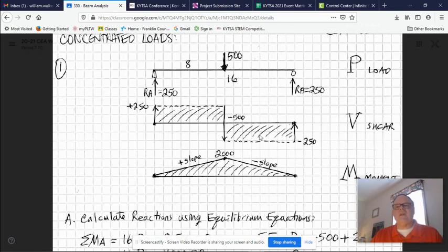Now there is a relationship between the shear and the moment. You draw another line down here representing the beam, and to get the moment, the shear value is actually the slope of the moment curve. Now there's a little bit of calculus tied into this. Those of you who studied calculus know that if you take the derivative of the line equation, you get the slope, and that's kind of what we're doing. So it tells me that the slope of the moment curve is positive.